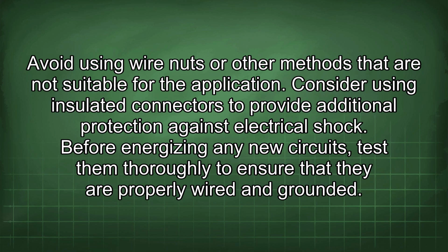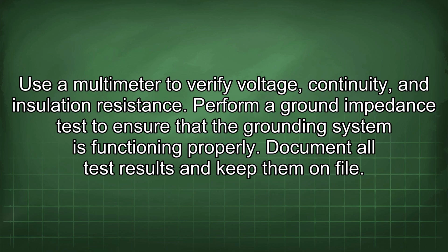Before energizing any new circuits, test them thoroughly to ensure that they are properly wired and grounded. Use a multimeter to verify voltage, continuity, and insulation resistance. Perform a ground impedance test to ensure that the grounding system is functioning properly. Document all test results and keep them on file.